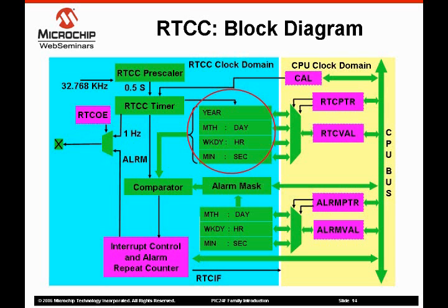The RTCC is fed directly from an external 32 kHz clock source. The 32 kHz signal is fed into a prescaler that provides the internal registers of the RTCC with a half-second pulse. The half-second pulse is used by the peripheral to update registers that contain data for the year, month, day, weekday, hour, minute, and second. These registers contain the time data in easy-to-use binary coded decimal, or BCD, giving the user time and date information in the format most often required to display it.